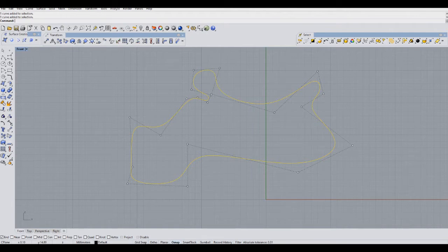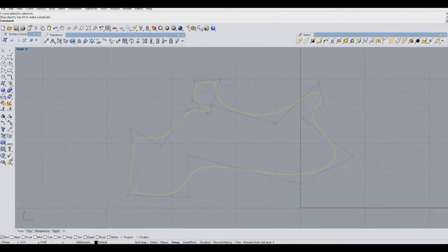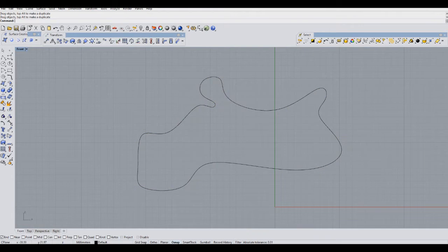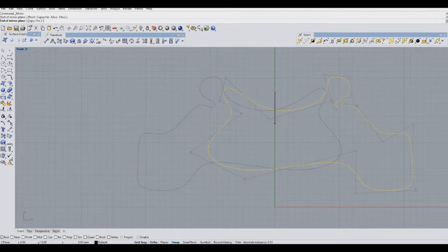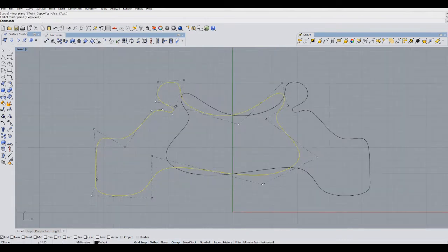That's rule number 1. Rule number 2 is the main transformation command that I use on one design can't be used in creating the design that comes after it. And what I mean by that is the basic commands that I use, things like drawing lines, drawing shapes, the trim command, which I use to cut things apart, that's not what I'm talking about. The major transformation commands would be things like mirror, where I take the shape and I flip it over an axis to make it symmetrical, either horizontally or vertically.